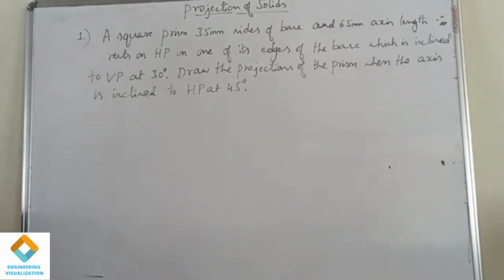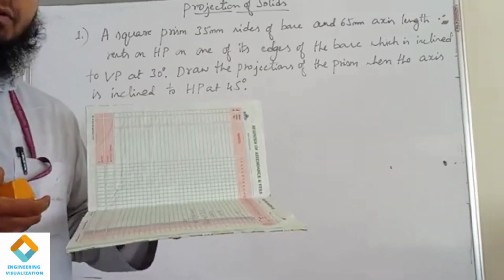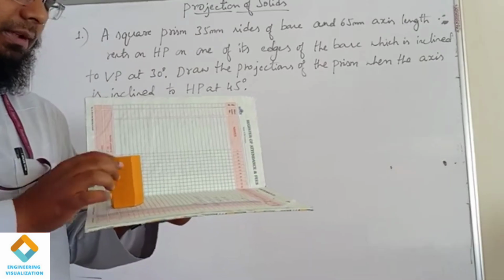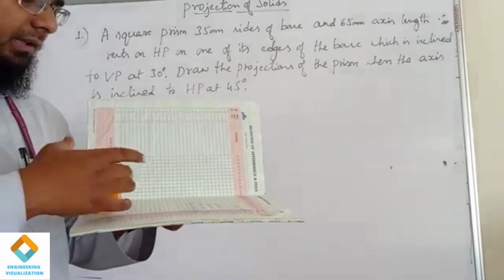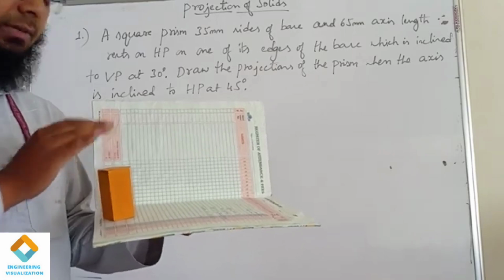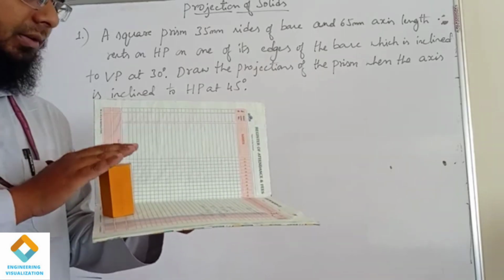So how the problem proceeds here, consider this is our first quadrant. Say this is our pentagonal prism. I am placing it with the right hand side reference, so right hand side reference means this side, right side. First position, drawing the top view, front view. You can see that you have two faces, top face and bottom face. Then drawing the top view, front view.